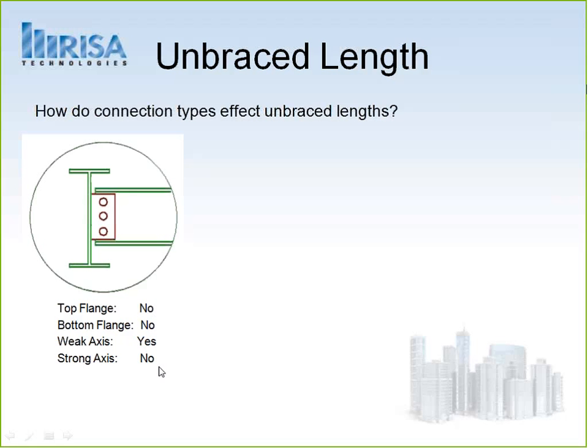So is the top flange connected in this picture? That would be no. The top flange is not connected, so we would not be bracing the top flange. And the bottom flange is not either in this picture. So we are just doing a clip here. We're not actually attaching to the top or the bottom. The weak axis would be braced by this beam coming in, and the strong axis would not be braced in this picture.